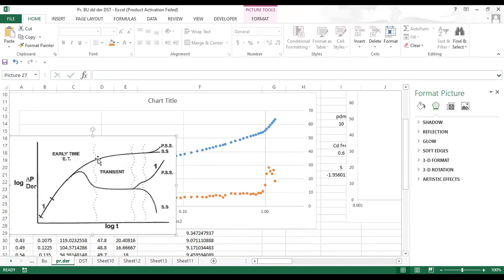So the pressure buildup continued like this, and it started to move up. You can see here there is a movement of points towards the top side of the axis. At the same time, these points also started to move up. Of course, they were a little bit random, but it is moving in the positive direction. So that represents the end of unsteady state flow here. Then after that, it attained pseudo steady state flow, but not steady state flow.